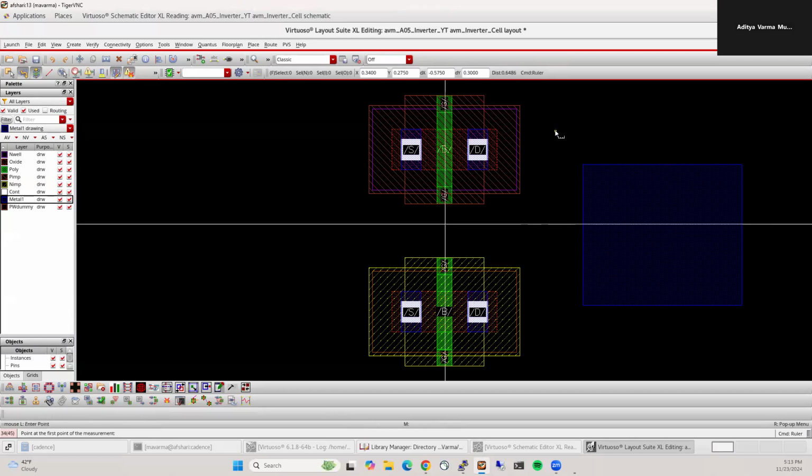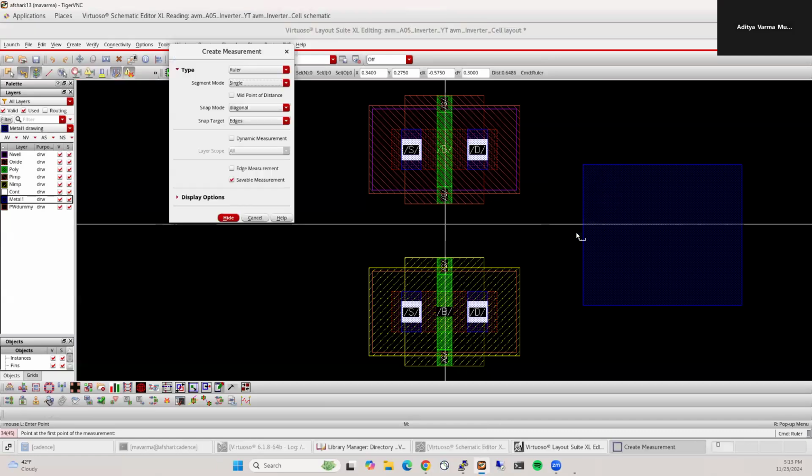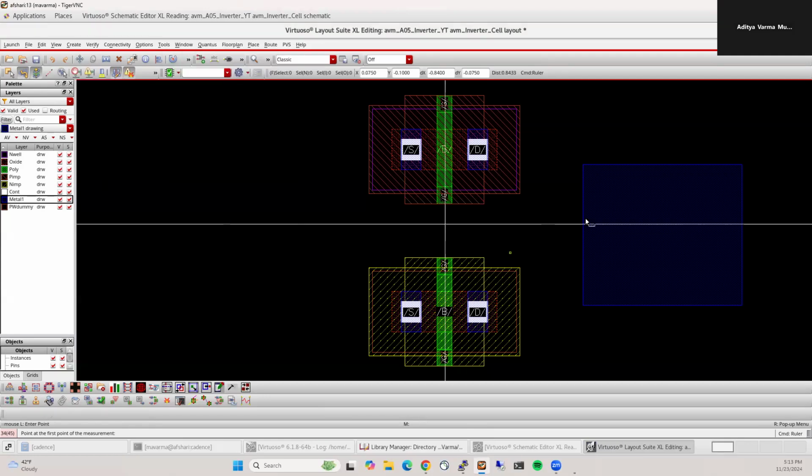So for example, if I again press K and then right click, go to options, you can make it multiple and you can also make it any angle. So that means that now you can go to any angle and do multiple sections and then double click at the end to get the full length. I prefer the diagonal over the any angle, and that's usually what I use, but many times I will use multiple sections. For example, if I want to measure the length of a meandered line or something like that. We'll use it in the future. Okay, so Shift K gets rid of it.